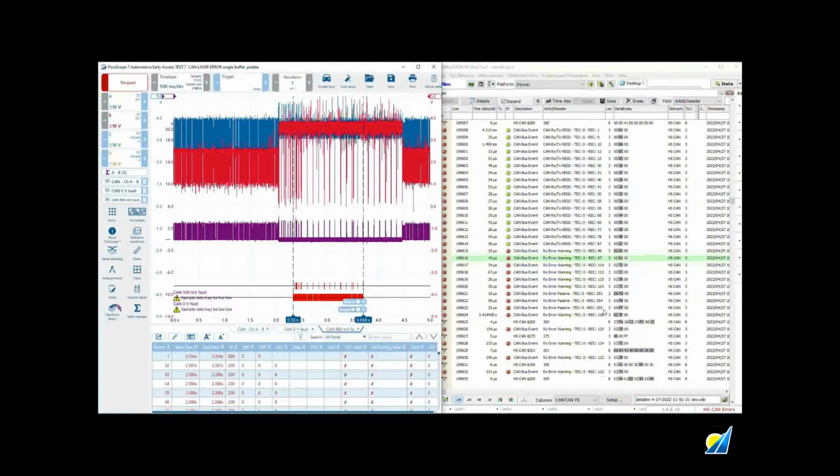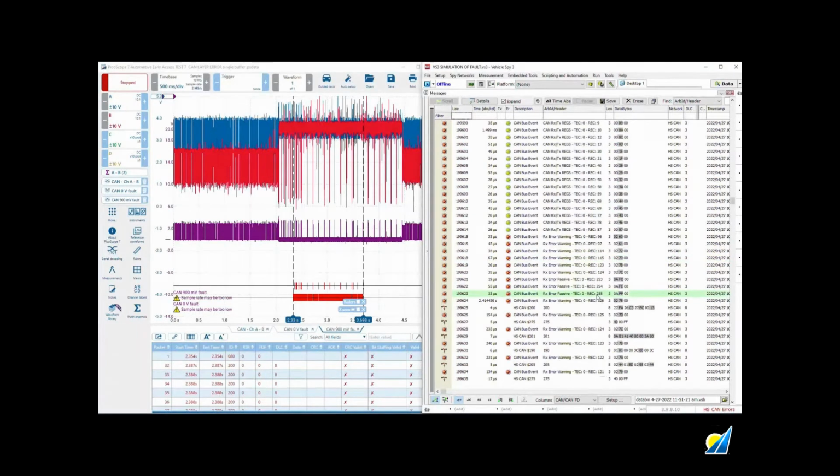But then it starts to decrement. So it's a bit of a confusion for me as to why that happened, but nevertheless, the fact that it's now back online and decrementing is what's happening right here. The bus has been restored. So one to note, when you see that 255, technically that should be a bus off state for the controller or a number of controllers.